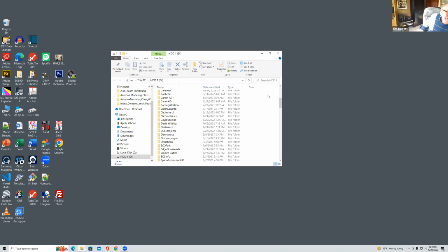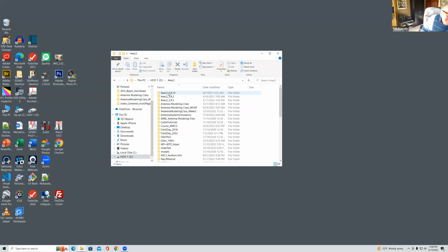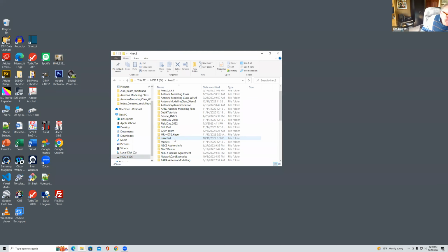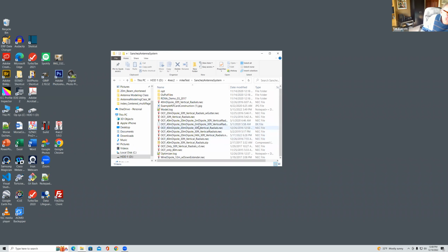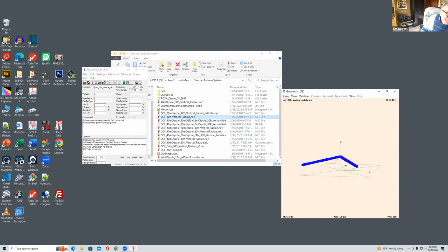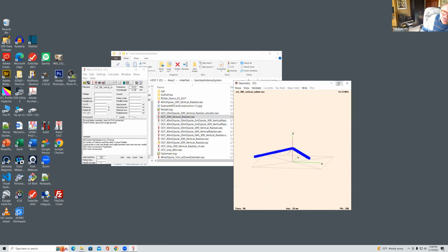You were asking what other people do. I had a vertical when I lived on a small plot, and now I have horizontal wire antennas because I've got room for them. You also asked about polarization, and other people may be more expert than me, but my understanding is that once it's been reflected over the ionosphere, the polarization changes. So I don't think that's really a consideration. It is more if you're on 2 meters, but it's much less of an issue for an HF antenna.